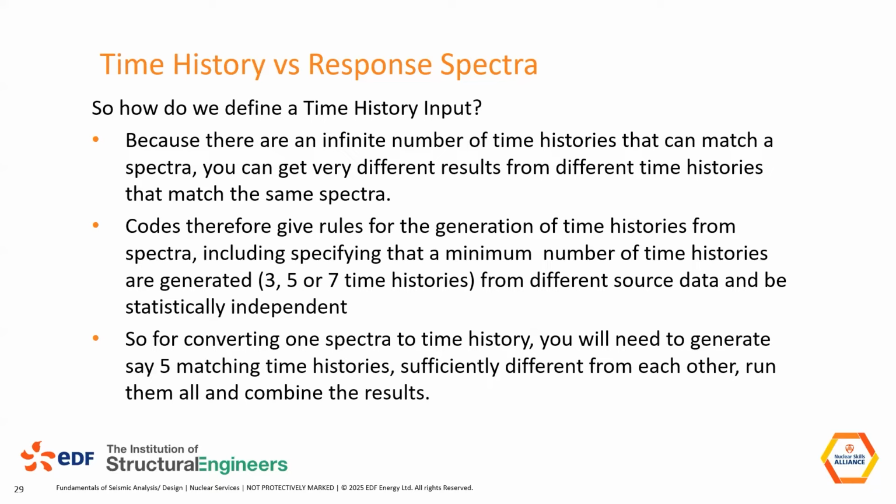How many you do depends on the code, and it depends on what you're doing. I think if you're doing a non-linear analysis, it might be 7. If you're doing something quite simple, it might be 3. In terms of how you do it, I don't have time to cover that. But there is software where you can take a seed input, a real earthquake, and modify it to match a spectra. The math for that is complicated, and I'm not going to cover it. But that's essentially what you do.